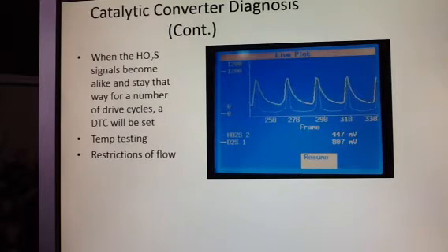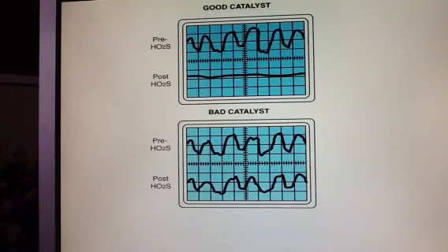It's telling us that it's getting very, very hot and it's a blockage. We can simply use our infrared temperature sensors to tell us that. And that gives us a simple indication. It does not tell us exactly what's wrong. There is further diagnostics with that. But it just does give us a simple indication that, hey, there may be something going on in that. With that, if we do have that kind of problem, we might have some sort of restriction of flow. If we do have restriction of flow, an easy indication is looking at that temperature testing that we're going to be able to have.